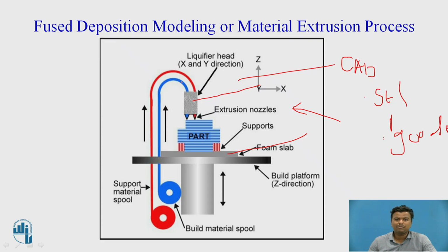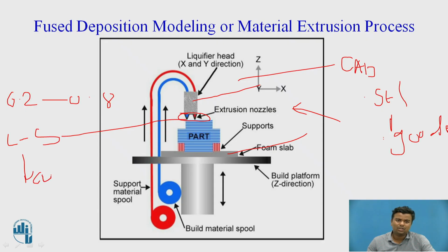The solid material passes through the extruder. The extrusion process is a formative manufacturing process in which the shape of a mold is taken by molten metal. Similarly, the molten thermoplastic material takes the shape of the very small diameter nozzle, varying from 0.2 to 0.8 mm. Whenever it comes through this point, the liquid is converted into a solid with the help of a curing process.